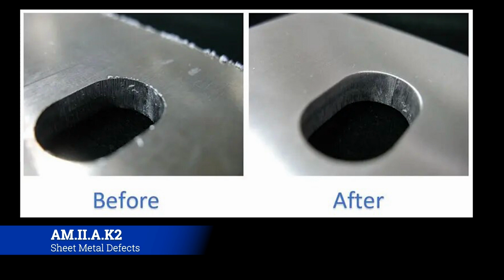Now, what is deburring? Whenever you drill or cut any sort of aluminum, a lot of times there's going to be these little flakes that form around the edges of the hole, and so deburring effectively just removes the burr from the edge. It's going to cut it off with the deburring tool, and a lot of times you're going to come by with some sort of abrasive cloth and then smooth it out. Scotch-Brite's usually probably the best one. It's not the most aggressive, so it makes this very nice, gentle, rounded hole like you see in the right picture that we're looking at.